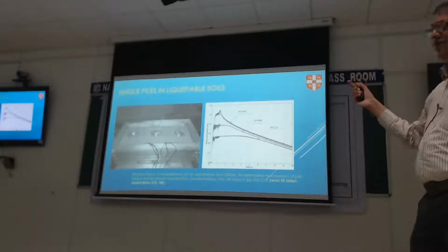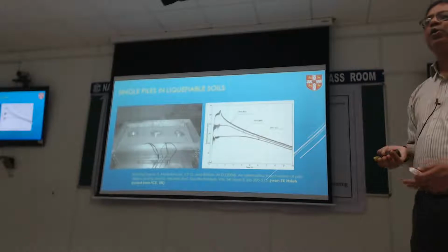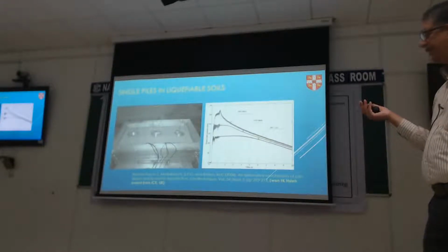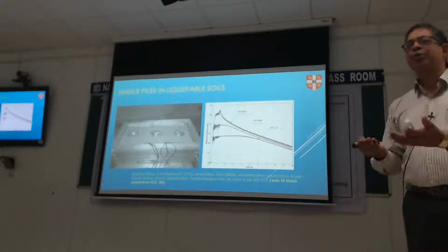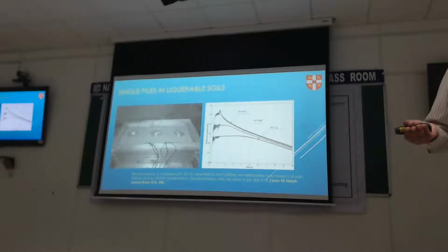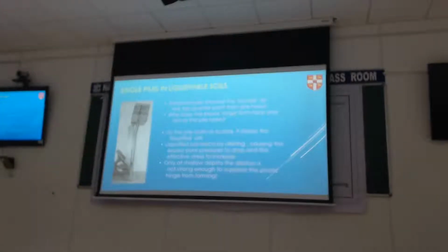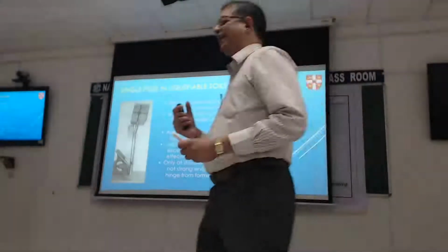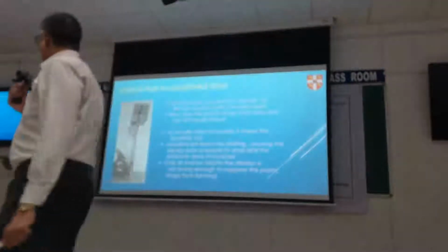The deeper ones get to a higher pore pressure. The shallow ones can't obviously go to the highest. You can only mobilize enough pore pressure until your effective stress becomes zero. After that, there's nothing the soil can do. But when we started extracting the piles, there's a problem.